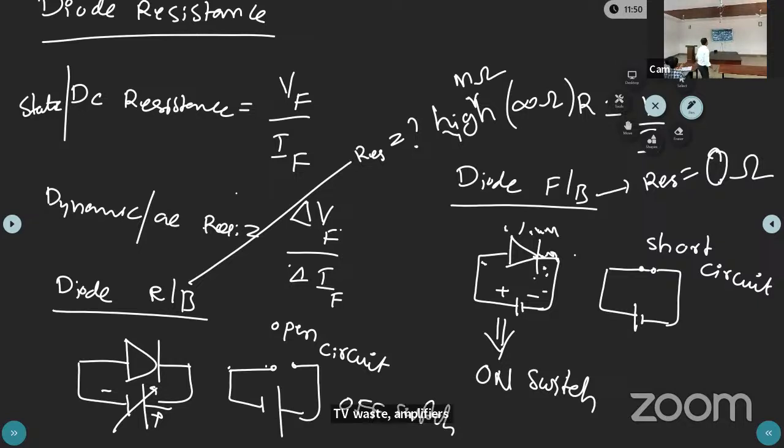Okay. Now, see, this diode has some limitations and some definitions. One is the maximum forward current. The maximum forward current means how much maximum current it will allow. That current is called the maximum forward current. Beyond that current, that diode will heat. So the diode will get damaged. Okay, that current is called the maximum forward current.